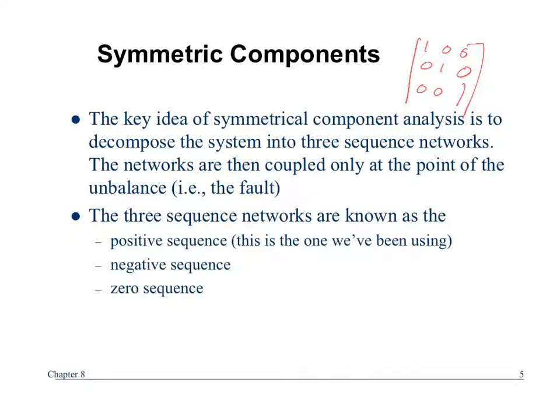We've already been looking at positive sequence. Remember how I talked about early in the semester? We said ABC rotation. That is positive sequence, and that's just the convention we've come up with to say ABC. The other one that we discussed briefly, but didn't spend too much time on, is ACB rotation. This is also called negative sequence rotation.